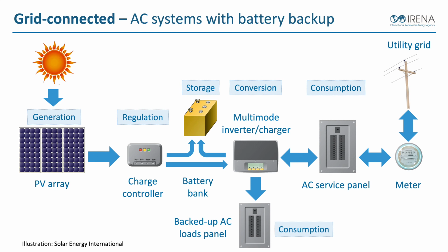And that multi-mode inverter charger is able to run my backed up loads panel in the event that the utility grid failed. The reason it's called multi-mode is that it can operate grid connected or like a standalone off-grid system, depending on what supplies of electricity are available at any given time. It gives us a more complicated system, but also a lot more capability.